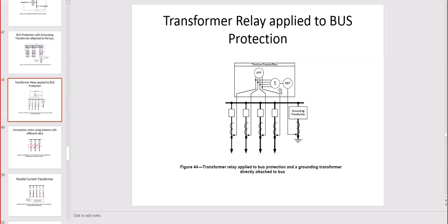In the past, the electromechanical relay did not have that possibility, so we would have a current transformer that does the summation of the other CTs and goes into the relay to trip. That output will be the vectorial summation of all currents from the feeders. New relays don't need a summation CT, and they do the summation inside the digital relay.